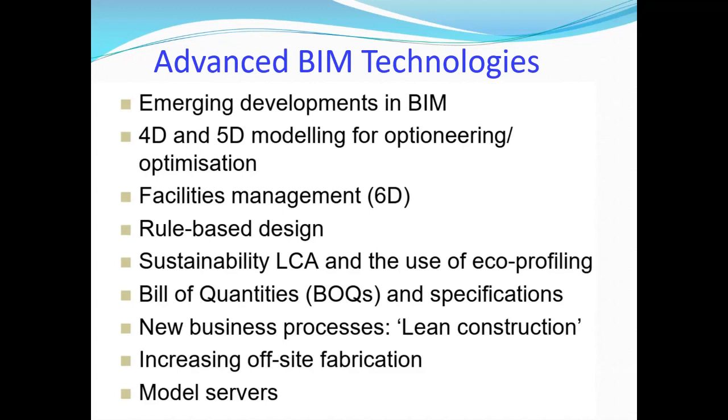Concrete volume is reduced, but formwork area increases. Formwork is costly. Then why would you go for this one? It's not value for money. It may look like an economical design because the quantity is less, but at the end of the day, from a cost point of view, it's not value for money because you are spending more money or almost equal money. Then why waste the time? If you have all this information in the model, you can do the analysis fast.